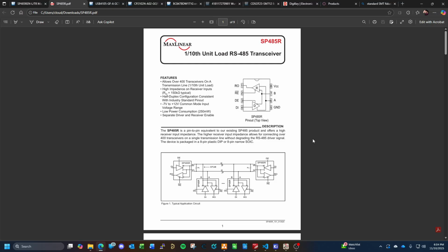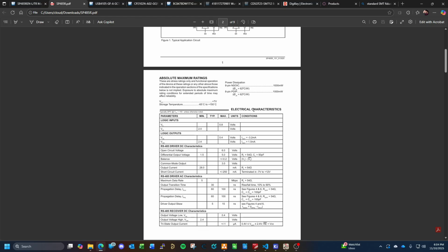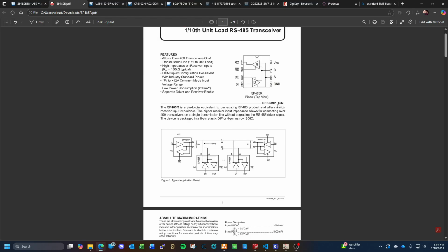If I'm not mistaken, the ESP32 has a drop-in for our RS-485. They handle the flow control, and I think we're going to need at least three pins to manage that, because the drive enable and the read enable pins can get tied together and controlled at the same time, because one is active high and the other is active low.